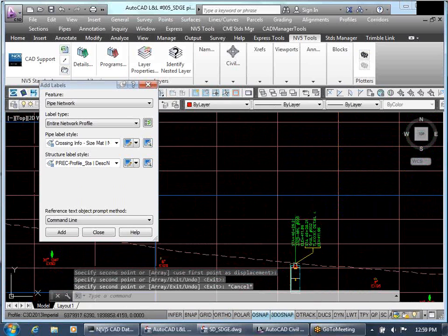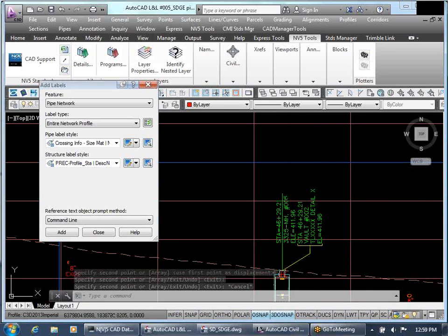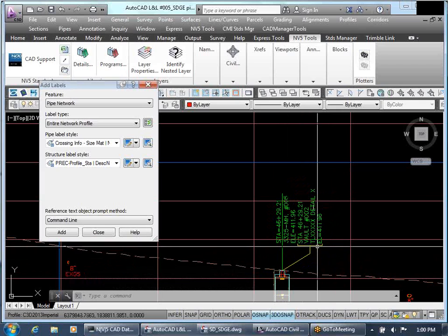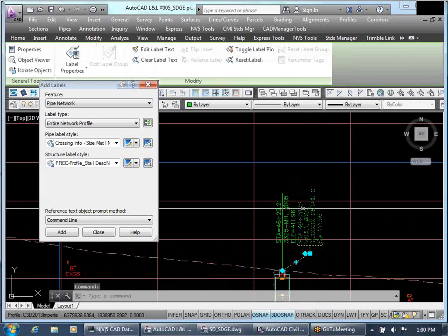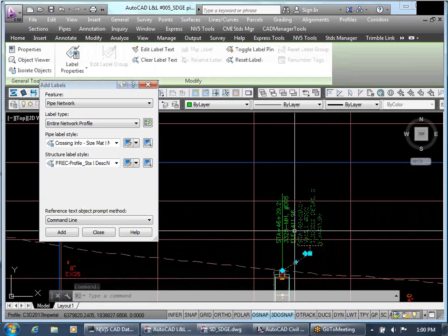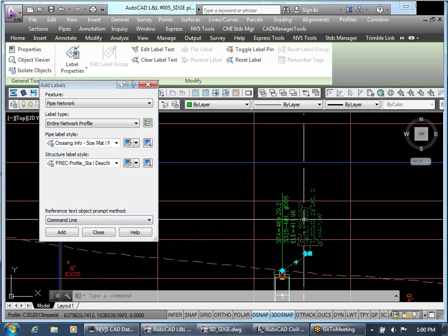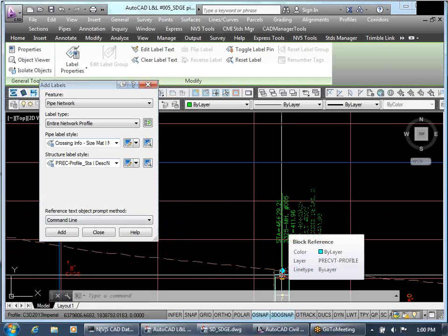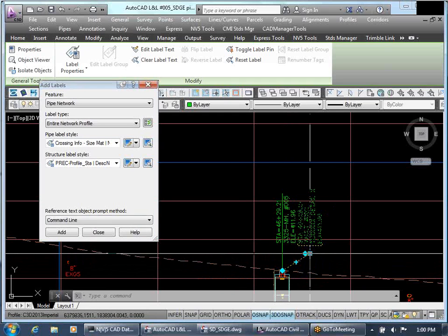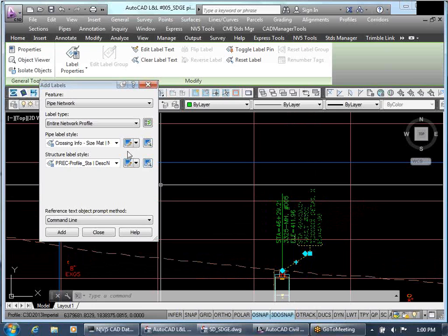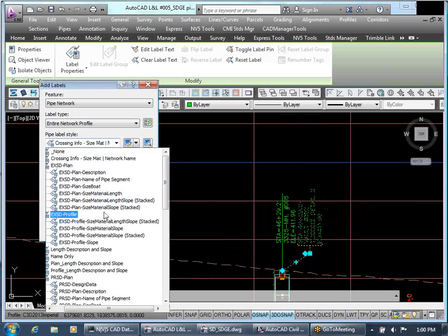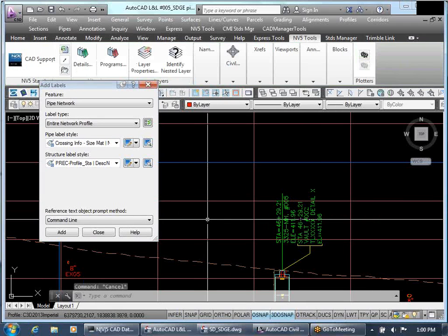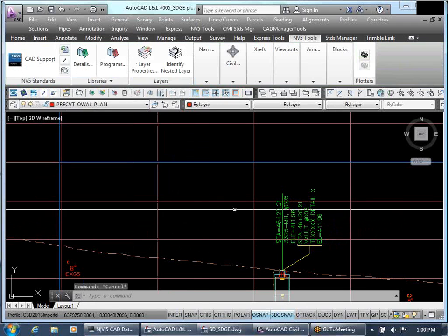However, you want to be sure to come back and change the style. Not all of these are 69 kV vaults. So you may want to have this be a style that you know needs to be changed. In the template, there's actually a style called Change Me, so that you can go back and remember to change these to the right style. I find that to be a quicker workflow in terms of copying the label and then going back down the line and changing the style versus trying to navigate this. Sometimes I find the Change Me style helps facilitate that workflow a little bit quicker.